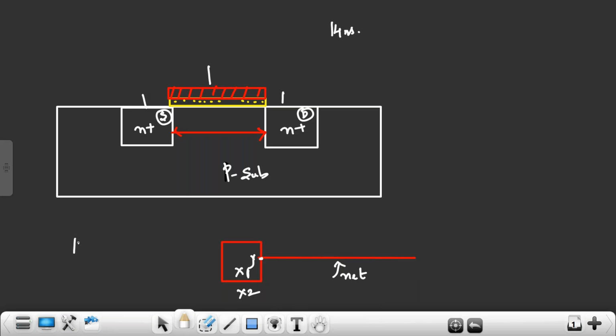So if you have 1,000 violations, you cannot do all of them one by one. For one net, you find the driver, find the drive strength, change the drive strength. Find the second net, find the driver, find its drive strength, upsize to the next level. Doing that continuously is not possible. Doing it for 1,000 violations is very time consuming. You require 4 to 5 hours.